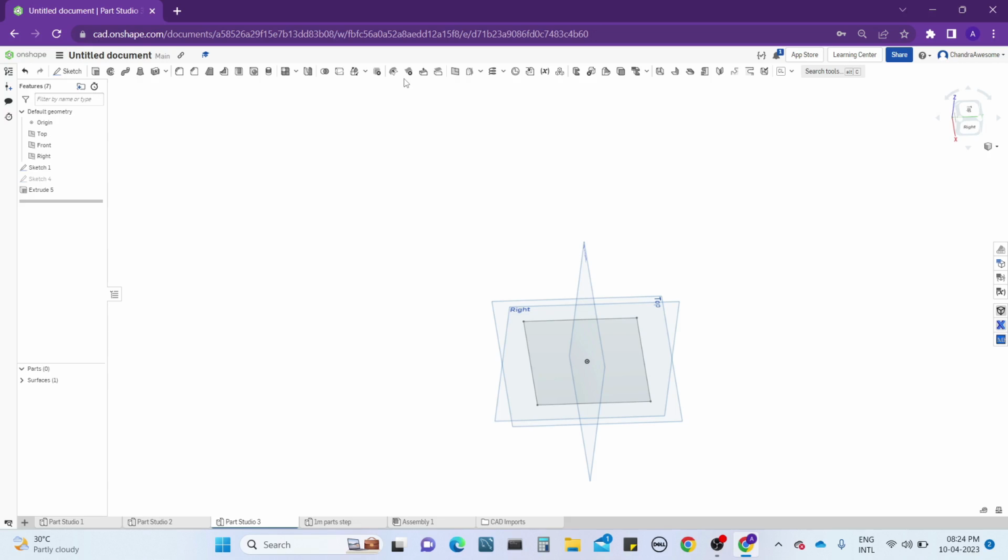When you create the initial fillet, for example, if you created a cube and gave it a fillet, and you want to change the fillet dimension, if you edit the previous design, there will be changes in the other design which follows the previous changes.